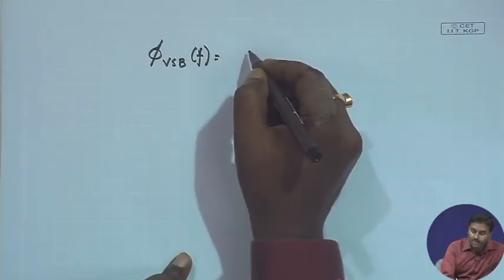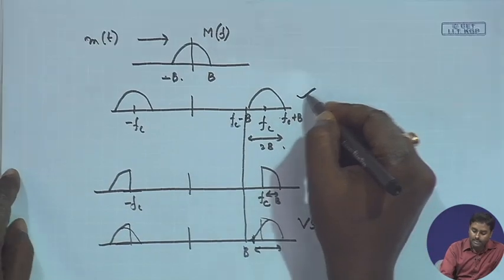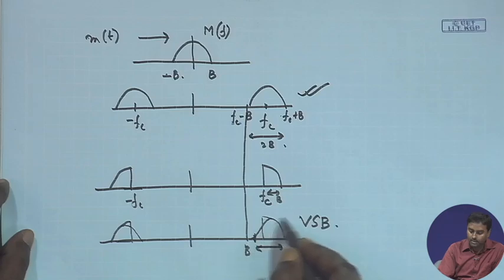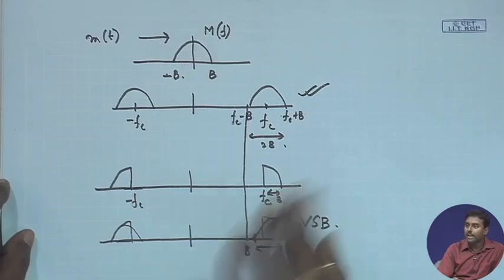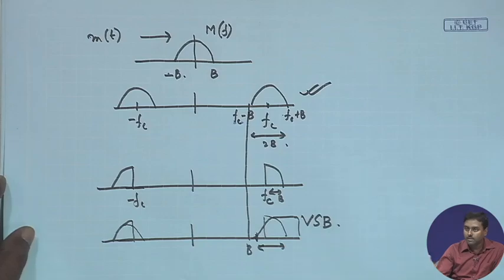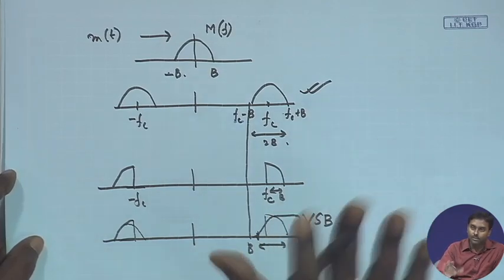It is nothing but the modulated signal, the VSB-SC, followed by a high pass filtering. It can be high pass or band pass, and you can end it later on. The upper part is not a problem, you can end anywhere. Only the lower part of the filter has to be properly designed.